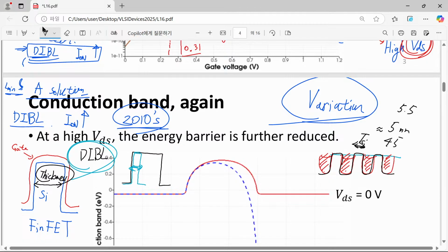If one is slightly wider and another slightly narrower, or if our etching is not perfect, so some part is etched a little bit further and some part a little bit less, then we will have fluctuation of our silicon fins, which will introduce fluctuation of fin thickness, and that is directly affecting the properties of our transistors. So that is quite a big problem.